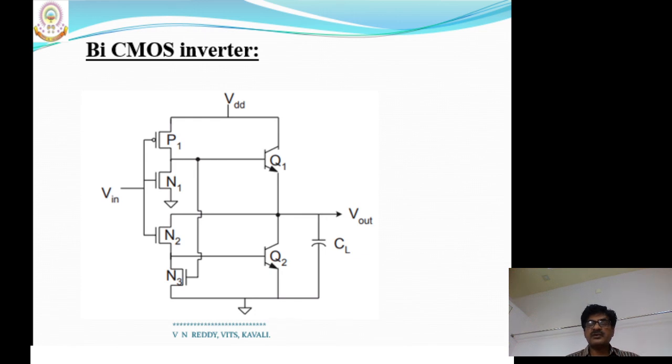So now the transistor Q1 is on, whereas Q2 is off. The output voltage is an open-circuited voltage, that is VDD, which is treated as a logic 1. So the output is definitely the complement of the input, and it works as an inverter. Because of the bipolar transistors at the output stage, a larger amount of current is supplied to charge the capacitor. In this way we can improve the speed, or reduce the delay. So that is the BiCMOS inverter.